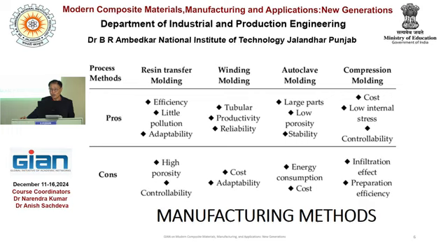In the compression molding case, the cost is very low, and there is low internal stress because it's very similar to steel plate compression. It's a very traditional process, but the infiltration effect is difficult, and preparation efficiency is very low.